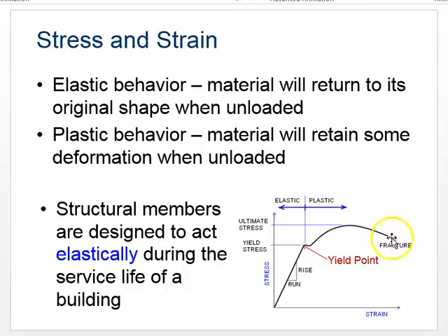From here forward, if I've stressed it to the point that it goes past the yield point, label that on your picture, if it goes past the yield point to this section, it will never return to its original shape and strength.